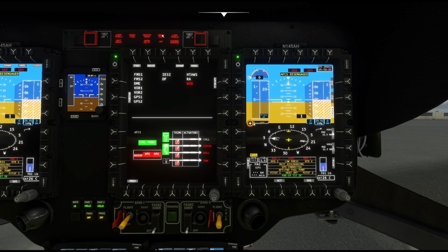So we will get rotor RPM. Engine 1 and 2 fail. We have main gearbox oil pressure, but we do not have it there because it is suppressed here. Obviously, the engines are not running. The rotor's not turning. No wonder we don't have main gearbox oil pressure. But this light is directly from the tap, so it's going to illuminate anyway. Our autopilot has failed because it's off, obviously. Suppressed here, but it's back up. It's up there. We got our battery overheat.